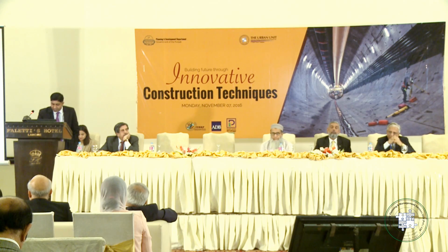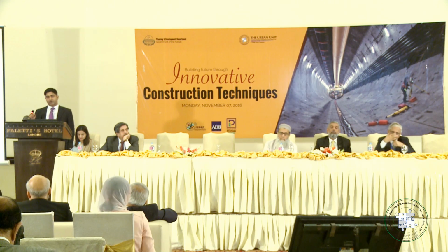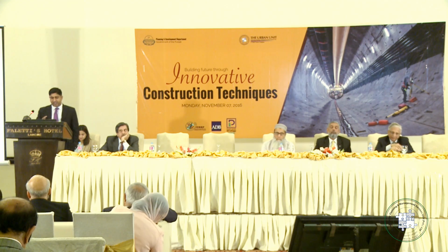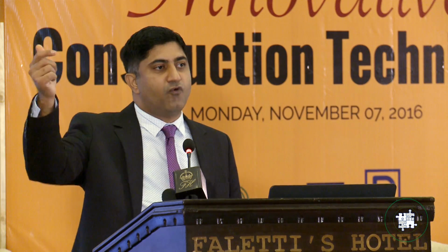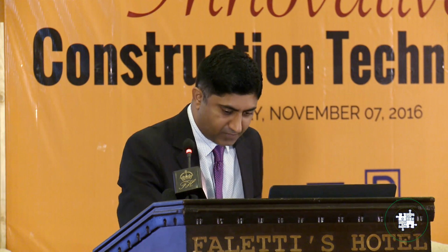We carry out in-house testing, we get the confidence, we go to an independent lab, we get more confidence, we apply this in the field, and we carry out site testing, and then if that is successful, we go for the large scale, full scale, accelerated pavement type of testing, or accelerated plate load testing.